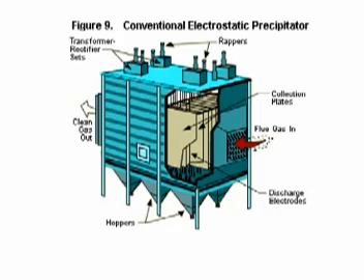Once the dust falls into the ESP hopper, it is either pneumatically collected, or, have you heard about fly ash ponds and things like that? What they do is bring a water pipe, and the water is mixed with the fly ash, and there is a sluice valve which rotates, and the fly ash keeps falling down. So you collect it dry or make a wet slurry.